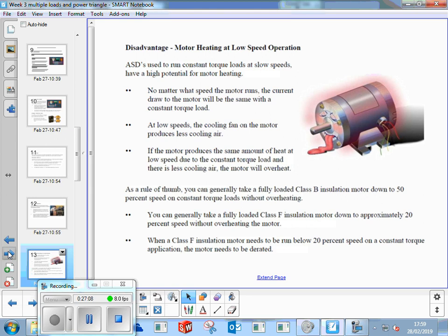Yeah. Well, after a short time, we made sure we locked out the programming of it, so there was, like you say, a minimum and maximum to what the frequency could be set to. So try as they like, they couldn't go below it. So it might be the class of motor they put on it.